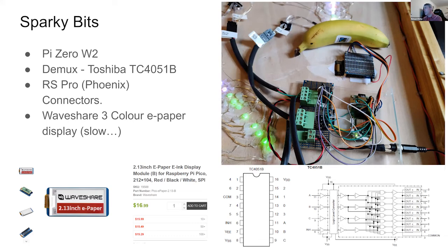Normally with NeoPixels, you just attach the strings. So if you have 100 NeoPixels here, the next string starts at pixel 100, and then it's 101, 102, 103, etc. So obviously 0 to 99 is here, and then this ends up being 100. But with these addressable ones, you have two zeros. So this is pixel 0 and this is pixel 0.